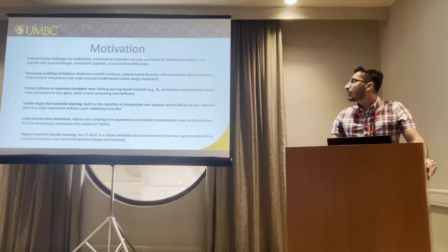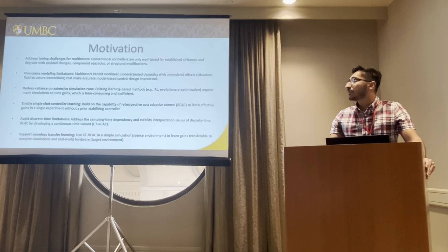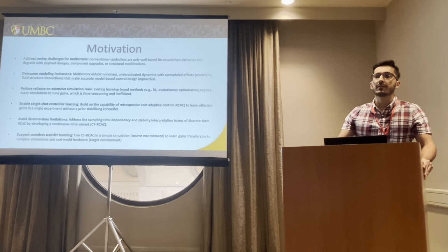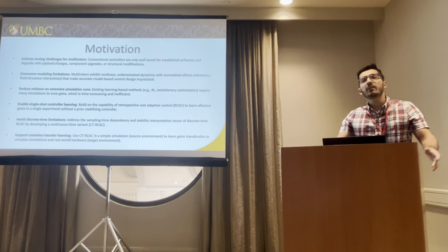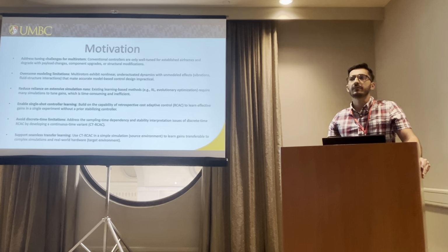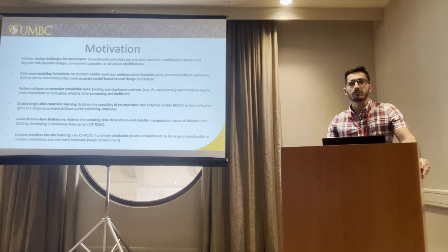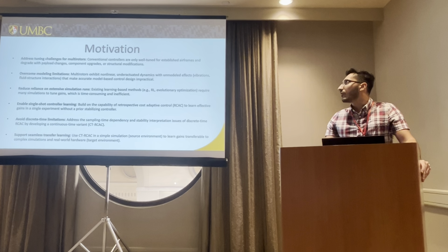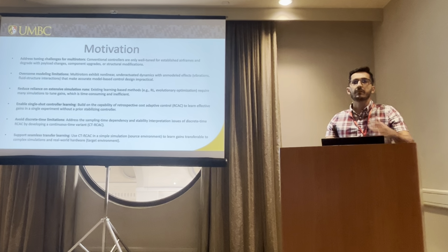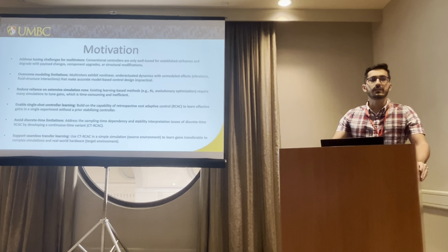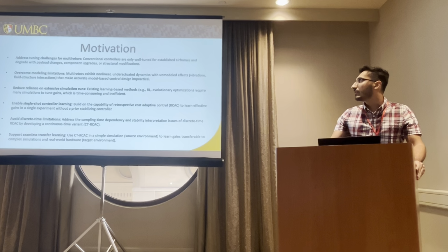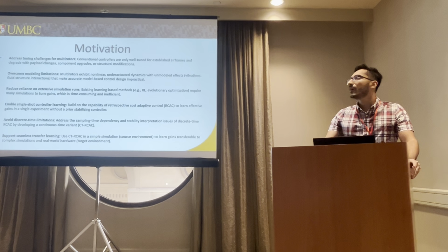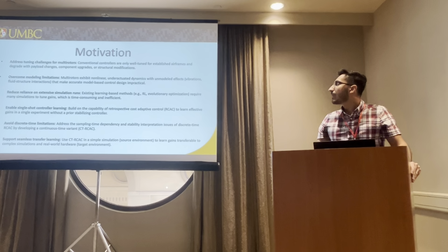There are some limitations on model-based approaches. For example, there are some dynamics that are really hard to model, for example the vibration effect of the motors on the structure, or fluid dynamics, the effect of propellers, the well-known ceiling effect and the ground effect. These are really hard to model. So the design of model-based approaches faces these challenges.